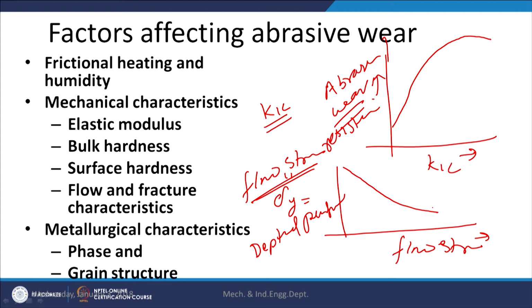Too high flow stress means the material will be of very high yield strength, it will lose its ductility, and hardness will increase. That situation may not be favorable, and the abrasive wear may start increasing, especially under impact conditions.